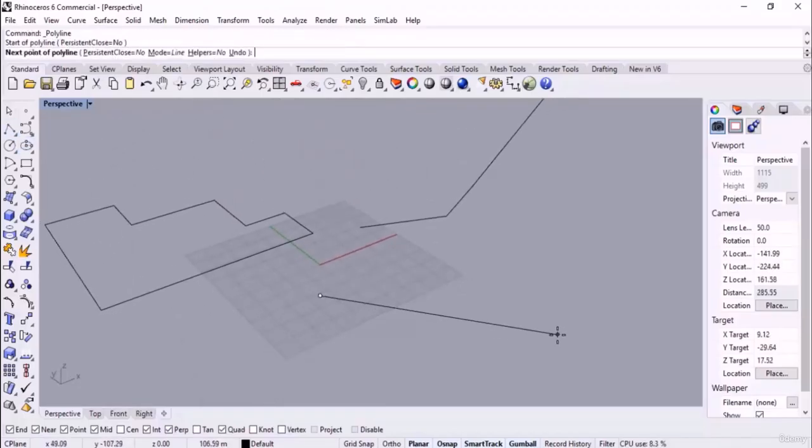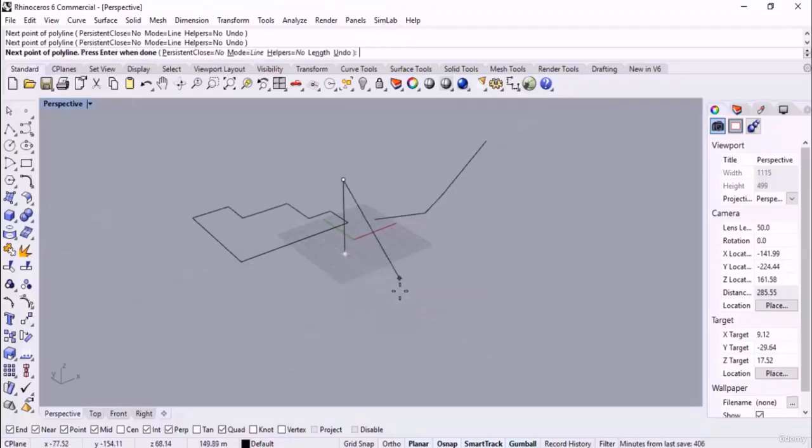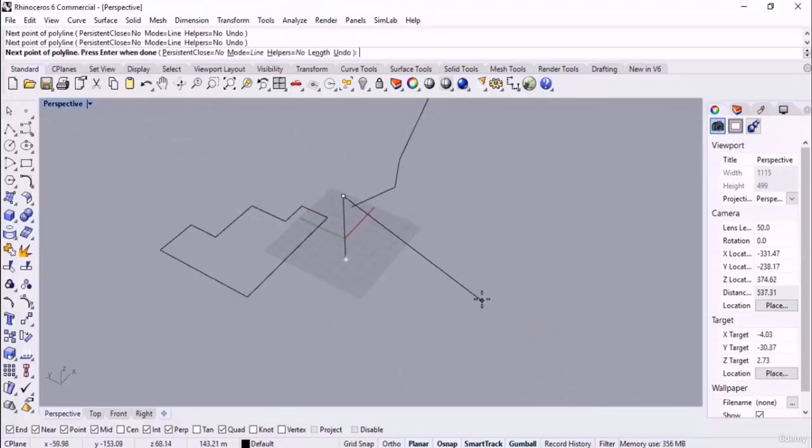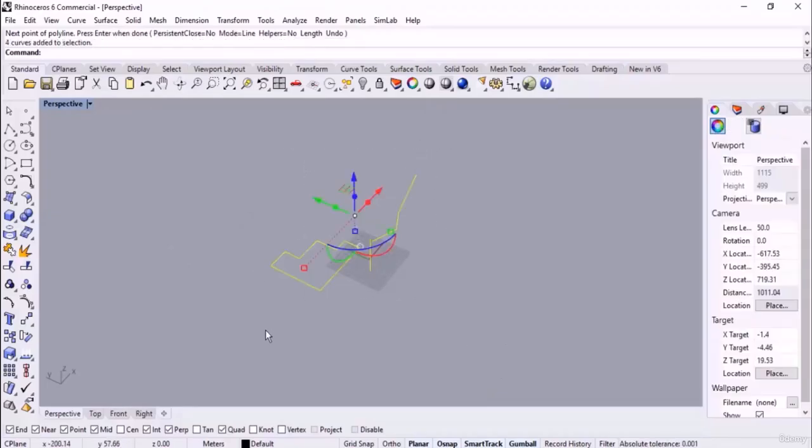I got a question for you. Here if I specify a point in the scene, then secondly I'm gonna specify the point overlapping on the previous one. I wanna hold down Control and then I click. What would happen? Let me tell that again. I have a specified point. Then for specifying the second point, I move the marker overlapping the previous point. I hold down Control and then I click. If I move the mouse, what shall happen? Yes, we will have a perpendicular line to the plane, as you can see, which is very practical. So don't forget to practice this lesson.